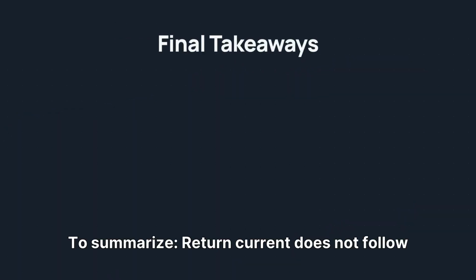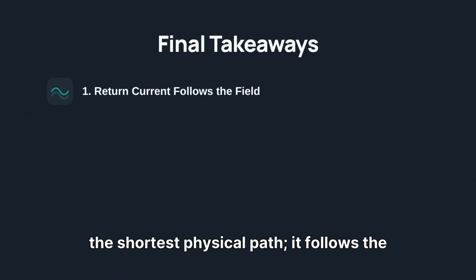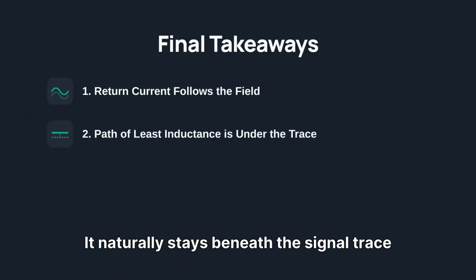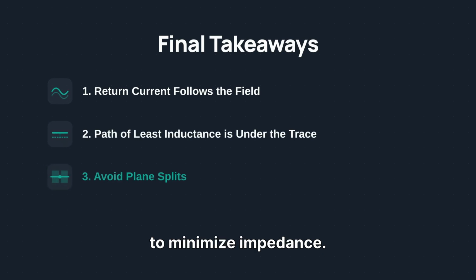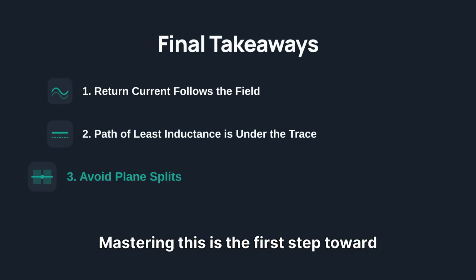To summarize, return current does not follow the shortest physical path. It follows the electromagnetic field. It naturally stays beneath the signal trace to minimize impedance. Mastering this is the first step toward professional high-speed design.